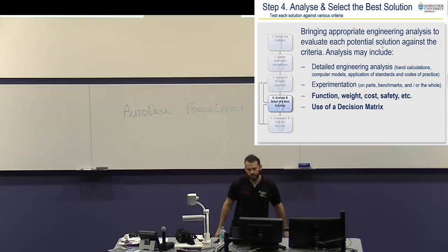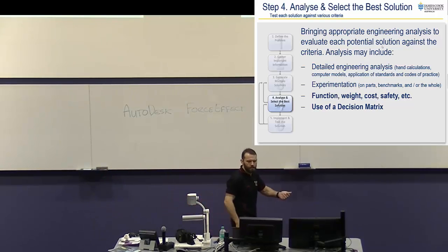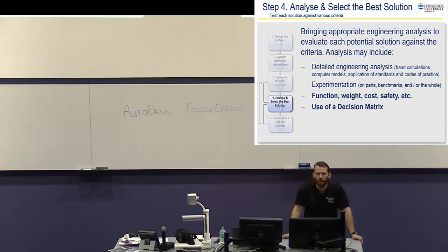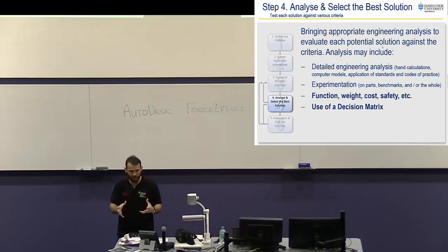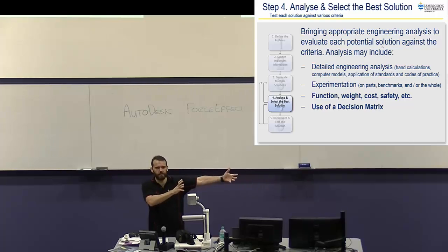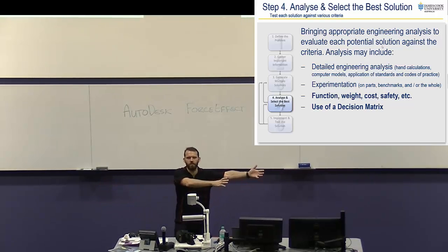Once you've resolved what sort of material you want to use and roughly what size that material is going to be, go back to your design and think particularly about total weight. If you've just tested a bit of material and you've got 3 different designs, and one of those designs needed a big thick bit of material and another needed a thin bit, you can start to calculate how much each design is going to weigh in total. It's not just that the fine one will be the lightest, because if you've only got 2 members in the thick one and 10 members in the small one, then that's going to be different.